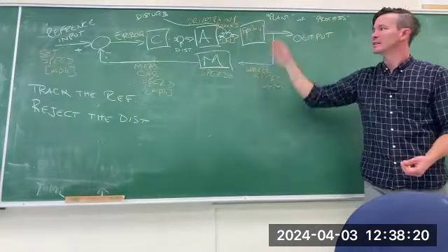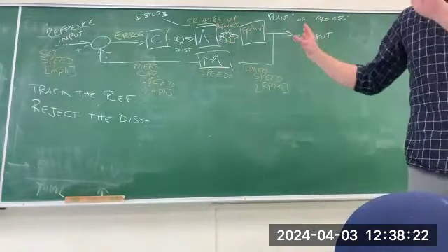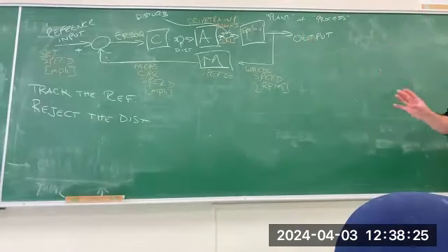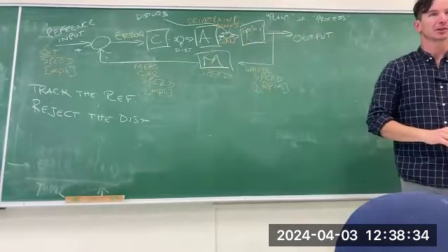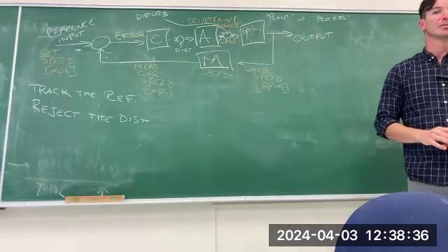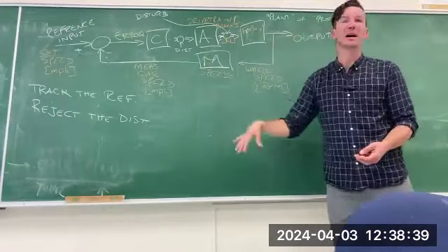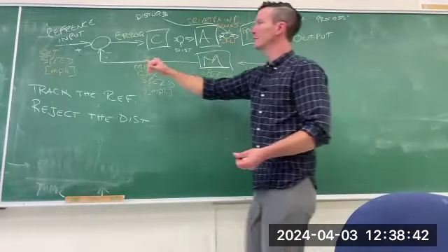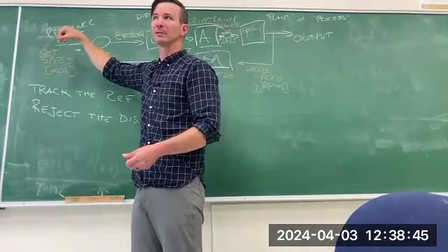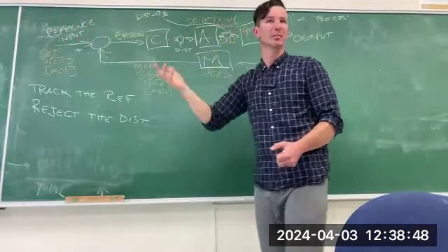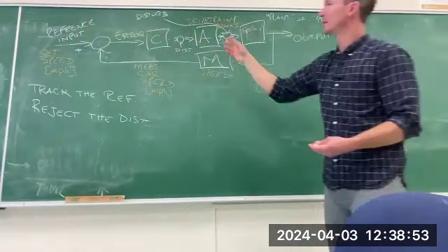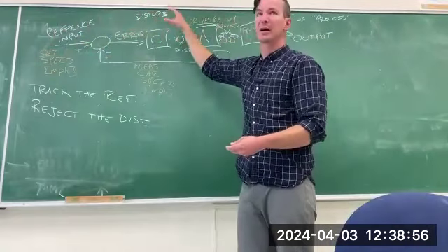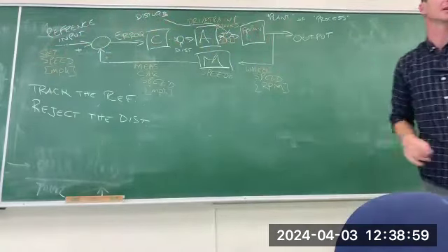Yeah, so I haven't put, is this time domain, is this S domain? This is basically just conceptually what is the order in which information is transferred throughout the system. We will deal with these block diagrams in the Laplace domain pretty much exclusively in this class. So what I mean to say is that we're going to make all kinds of LTI assumptions, but the signals themselves are definitely time varying. If the signal wasn't time varying, it would be a really boring control system. And if either of the inputs are time varying, then that guarantees that the intermediate signals are going to be time varying as well.